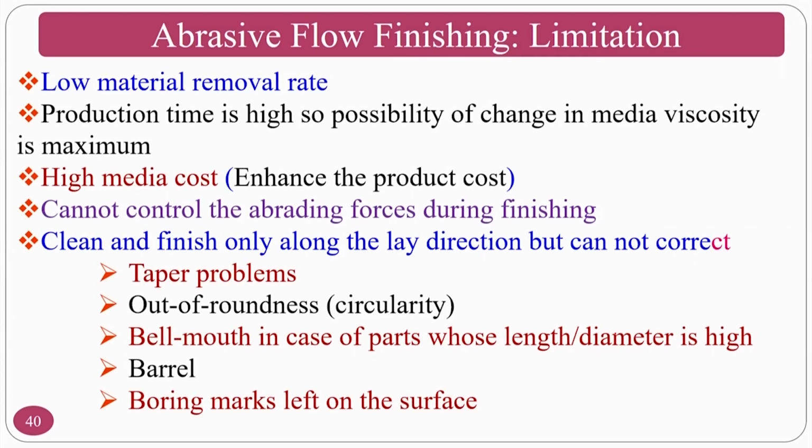This process has limitations, like low material removal rate. Production time is very high because as you increase the finishing time, the viscosity of the medium will go down, and the medium cost is very high. If you want to go for a commercial medium, normally the medium is too expensive. So, the production cost of your finished component goes up.